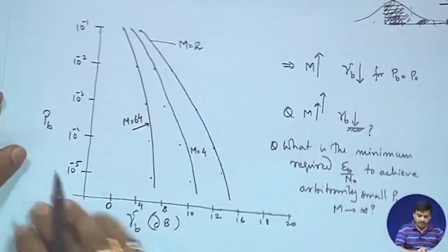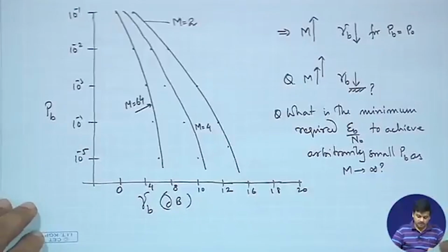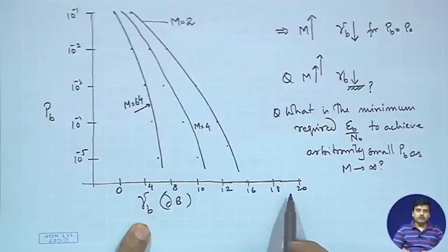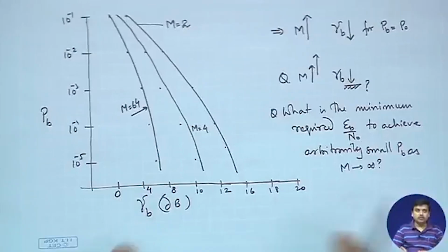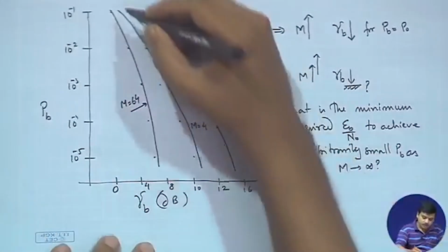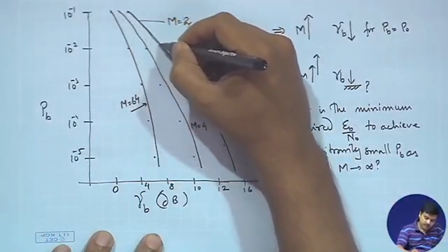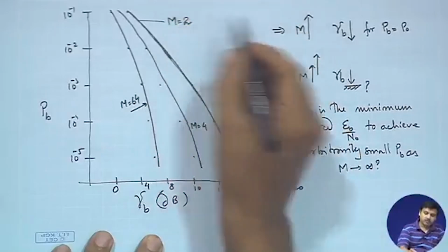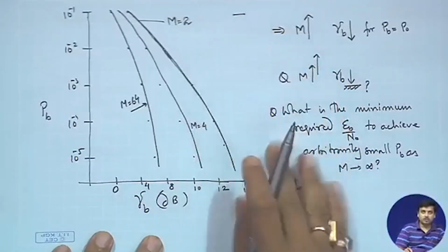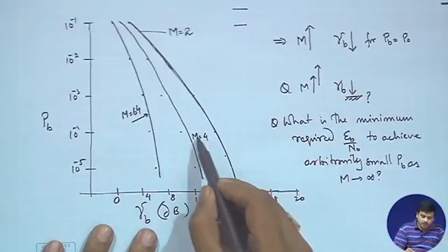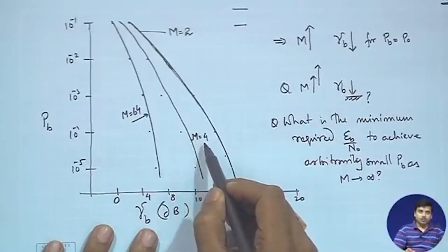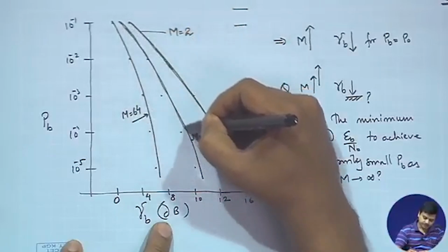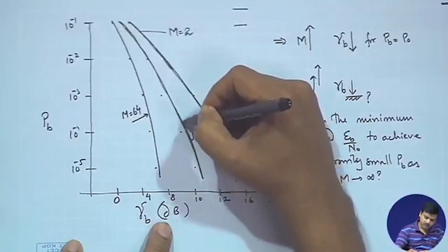what we can have is the probability of error curves versus Eb by N naught, which we have plotted over here, and it might be quite interesting to look at this particular result. What we have here is this curve, which is the probability of error for m equals 2. That means you have only 2 signals to choose from, right. Whereas, when m is equal to 4, we find that the curve is moving in the left direction. That means it is going towards the left.